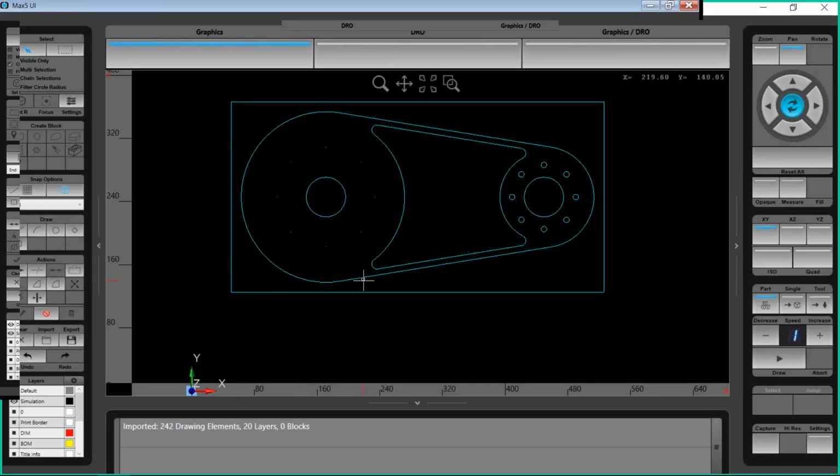And then as you cursor over that contour, it'll snap to the end point of one of the pieces of geometry, whether it be the line or the arc. So wherever that snap is, when you select the geometry, that is where the start point is going to be. Does that answer your question, or are you asking if you can edit it after you've made the block?